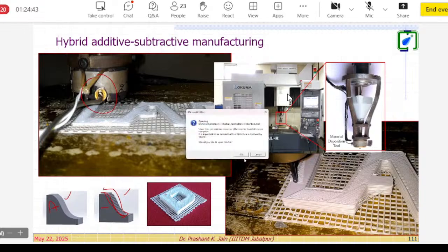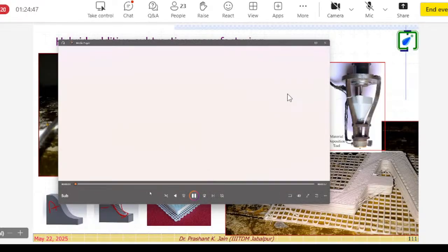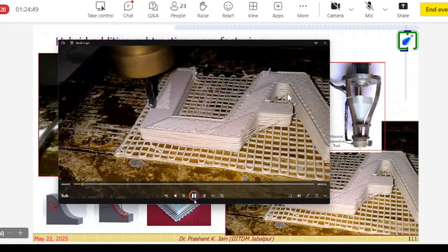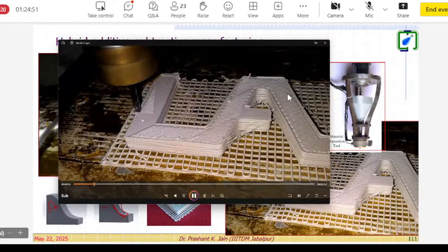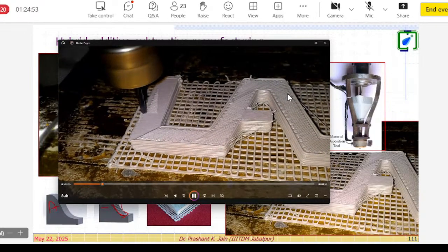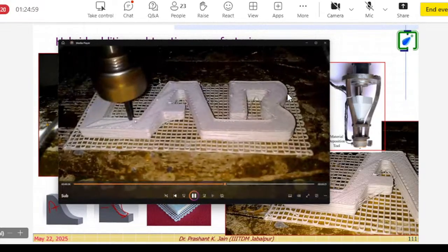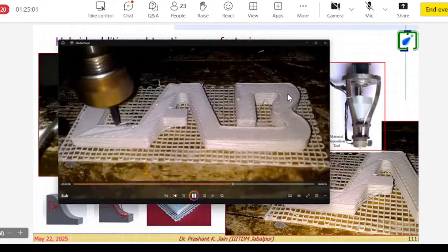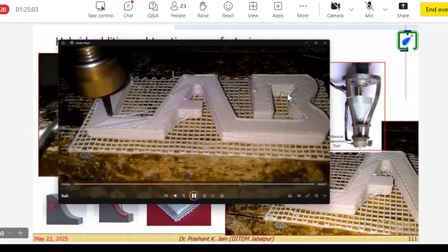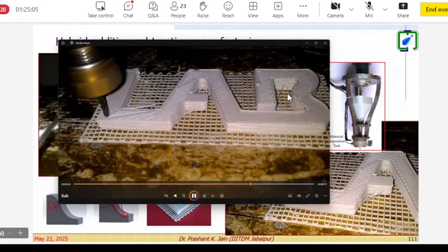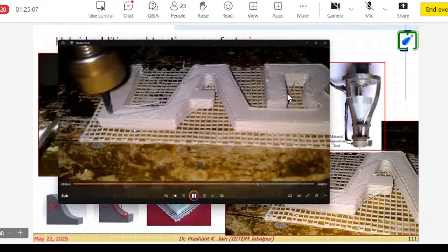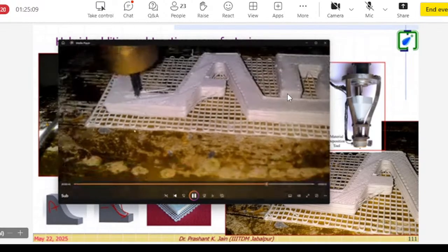See, in this case again, on the top surface you will find different triangles, right? So this is working in a triangular manner. One triangle, second triangle like this. Let me move ahead. So you see over here, this is moving again in a triangular fashion, right? Because on the top surface, due to the STL file, you have the triangles. So it is taking one top triangle at a time and machining it, right?